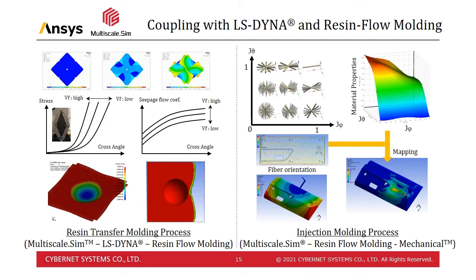However, we have to remember that there is a dry fabric in the casting mold. Anisotropic flow resistance is distributed due to the presence of dry fabrics. To make matters worse, the density and orientation of the fibers influence the flow resistance depending on the molding history of the press molding process. That's why we have to perform the analysis for press molding.